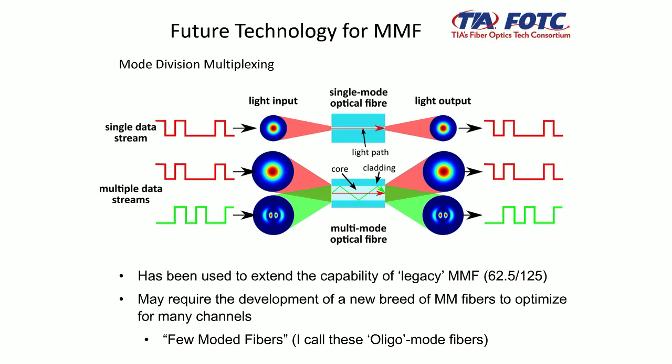Well, with multimode fibers, we have multiple modes. We have multiple fundamental modes. We've got, in fact, 19 mode groups. And each of these mode groups theoretically could act as separate channels. If I could excite these mode groups separately, I could have multiple channels. So I can theoretically have up to, if I used a 50/125 fiber, up to 19 channels in a single multimode fiber.